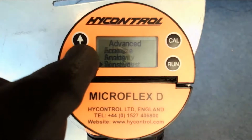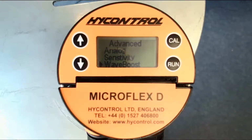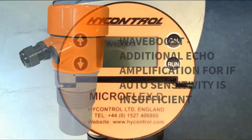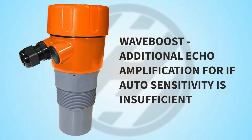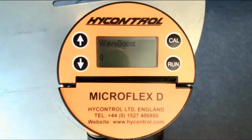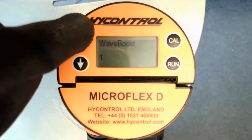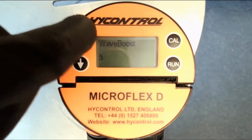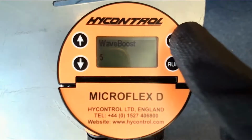Press the down arrow once more. Now we have the wave boost. Press the Cal button to go into the menu here. This adds another step of sensitivity in addition to our last parameter and will boost the gain and the amplification to the echo when needed if the echo becomes weak at any point. We can use the up arrow to adjust this. Only really necessary when the sensitivity has been maxed out at 20. Press Cal to accept this.